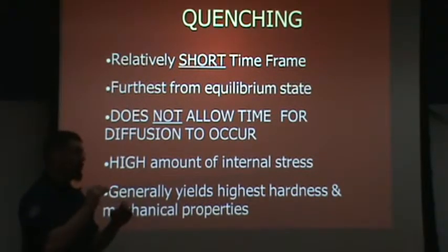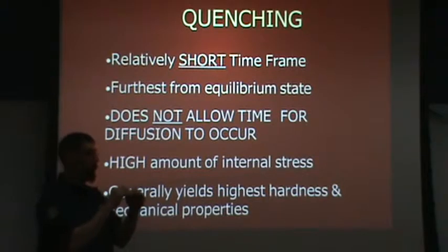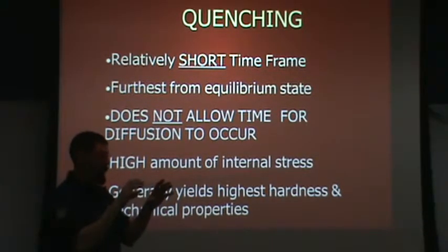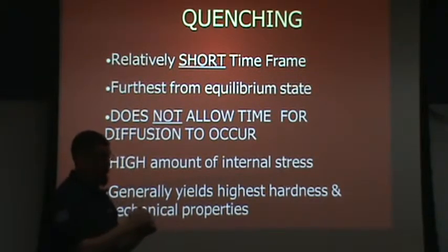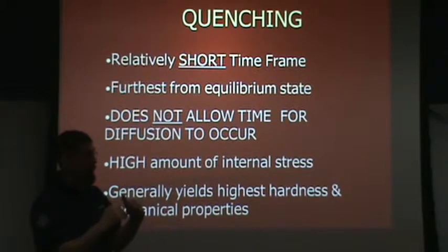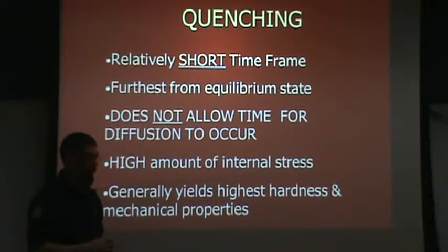The activation energy that I put in thermal heat will determine what grain size I get, provided I have grain refiners present. So if I go to 1750 in my normalize, I'll get one grain size. If I come back and austenitize the second time at say 1650, I'm 100 degrees lower, there's less energy, so the grains won't get quite as big. And that means they'll be a little bit smaller than they were after the normalizing cycle.